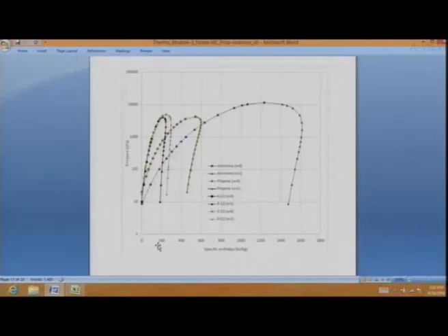And so we could make all these property plots of different substances on this. Water tables that you see, there the specific enthalpy of saturated liquid water at triple point is set to 0. So I cannot just make that plot and plot h of that on this. They will look fine, but actually they are quite different there. The whole thing will have to be shifted quite a ways out.